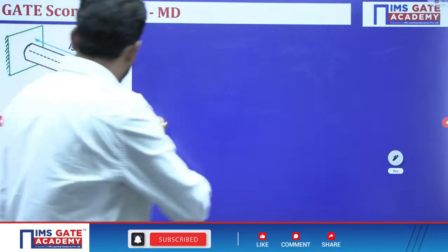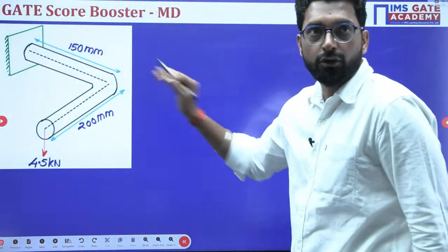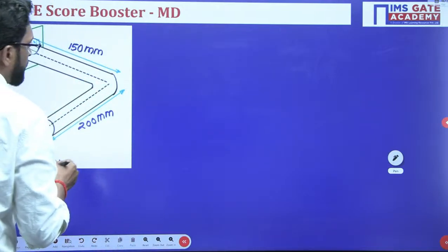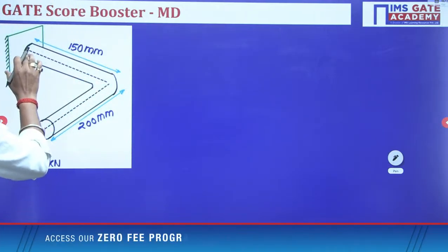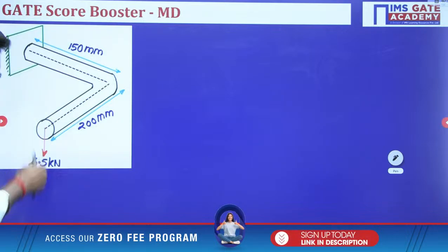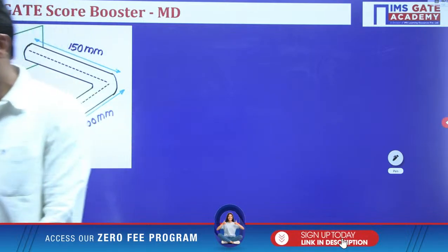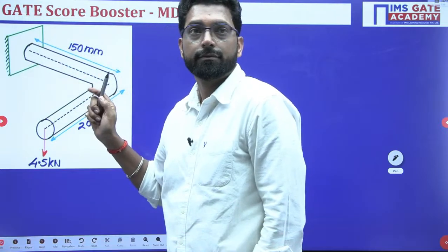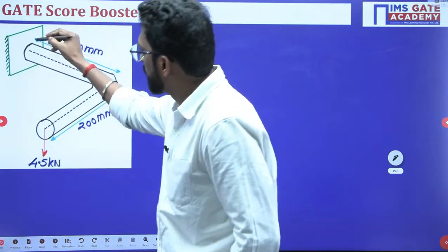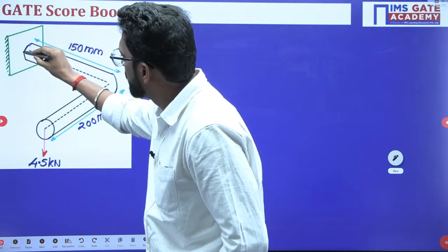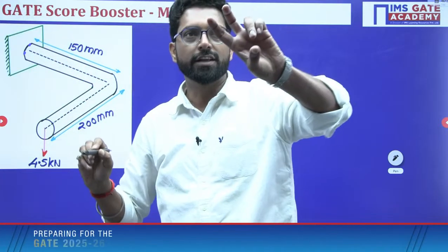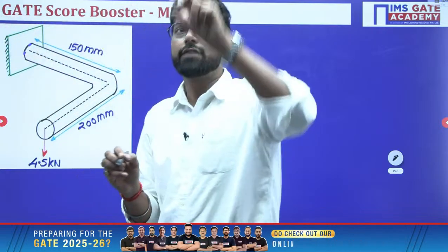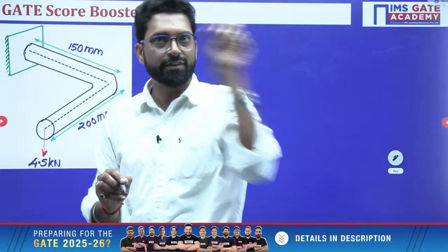So these are the questions. The figure is given in the question. So what do we have to do here? See this one, there is a shaft. This end is fixed. If you apply the load, first I identify which section is the critical section. Let's suppose there is point A and point B. The shaft base is circular, so you take 4 points: top, bottom, left and right.